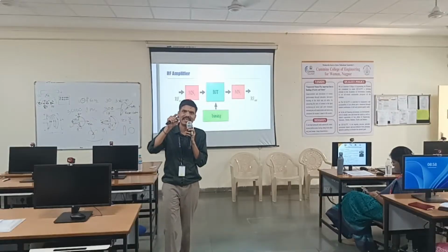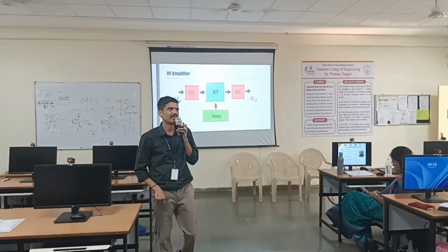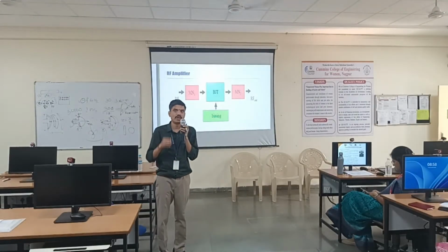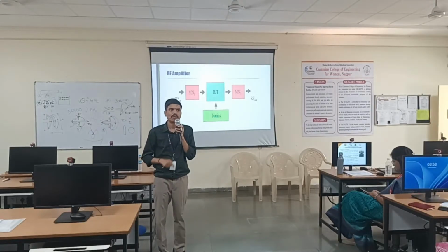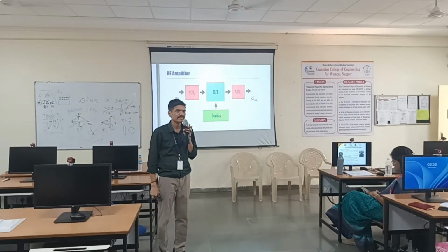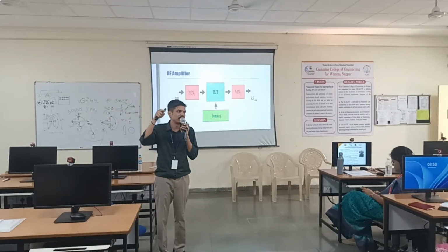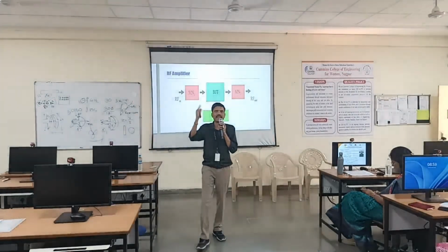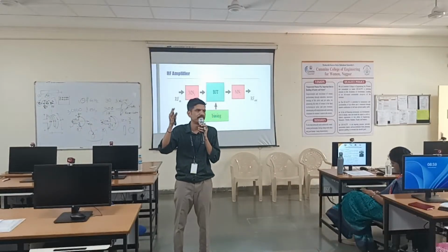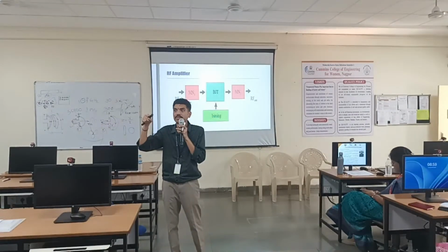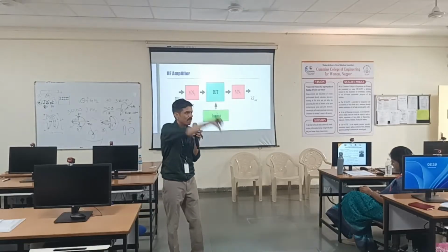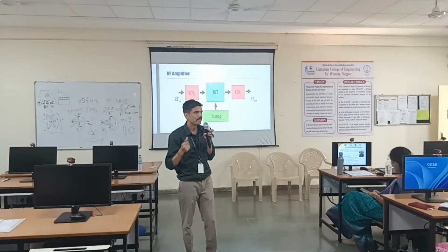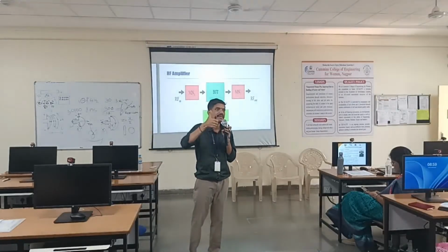This is thickness only. If you take the epsilon r, dielectric constant, what is the requirement for antenna? What is the requirement for circuits? Because you want your antennas as small as possible, right? So what should be the dielectric constant? Lambda g is lambda 0 upon under root of epsilon r. Do I need to write that equation on the board? The conversion between guided wavelength, free space wavelength and epsilon r, relation among them. Lambda g is equal to lambda 0 upon under root of epsilon r. Higher epsilon r, lower lambda g. So smaller and smaller antennas we can design if you use high epsilon r dielectric substrate.